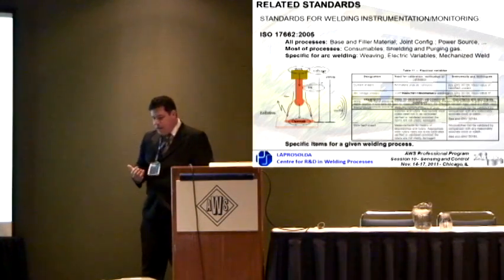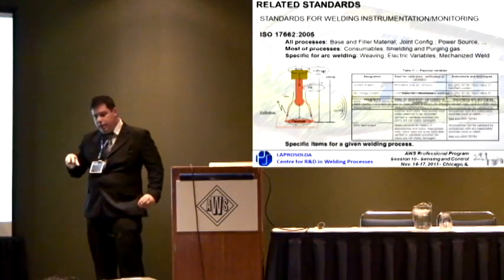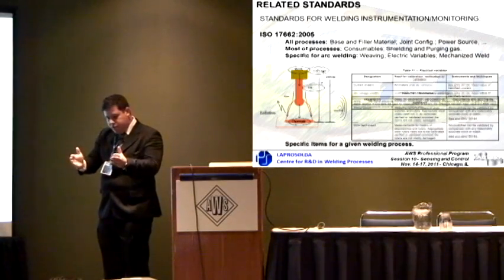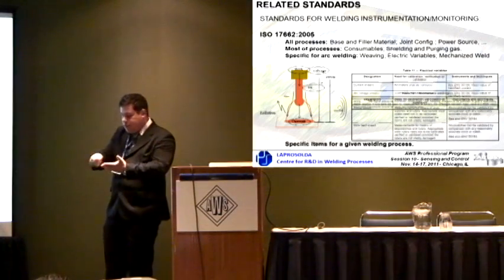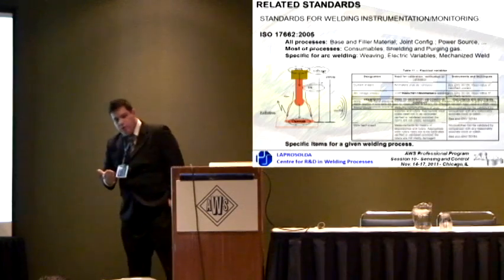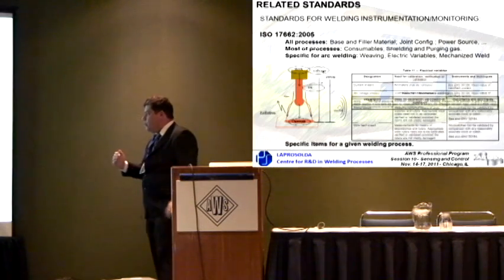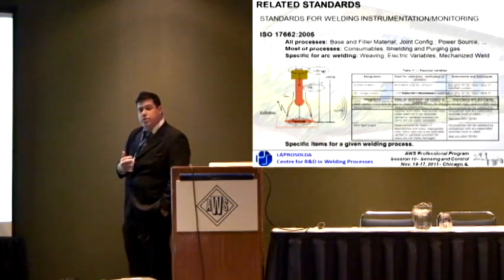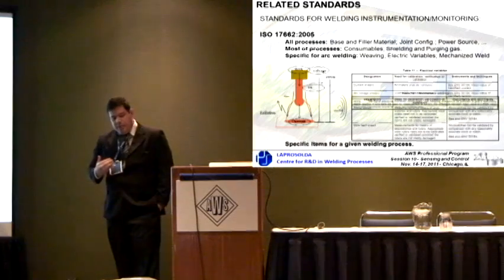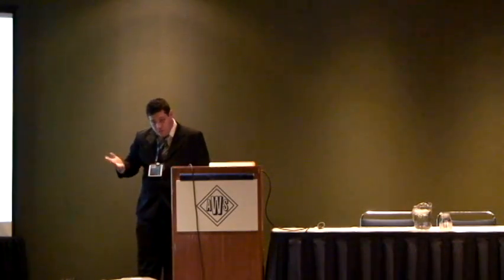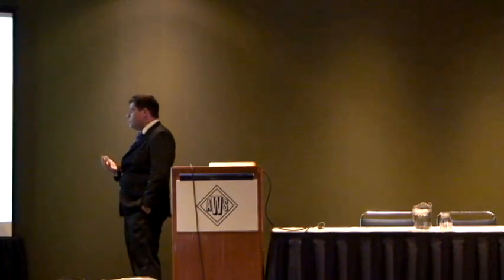By measuring, I mean we need to acquire the data and store it. It could be simple: a consumable arrives, say an ER70S-6 wire, so I write down the diameter and the type of the wire. That's a simple measure, and we don't need to really acquire data. That is not true if you have to measure current and voltage values. In that case you can simply store the mean and RMS values, one every second, or one every two to three seconds. That's what we really need.